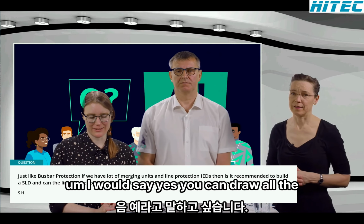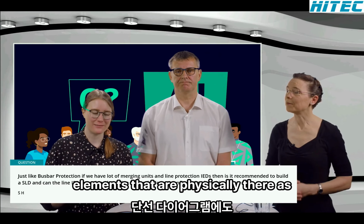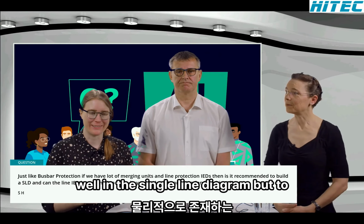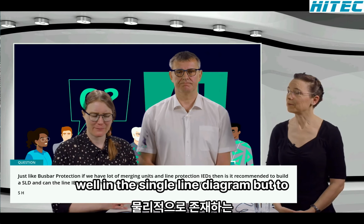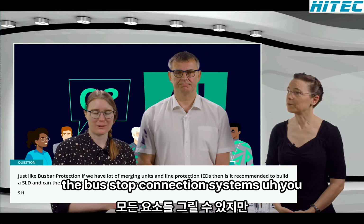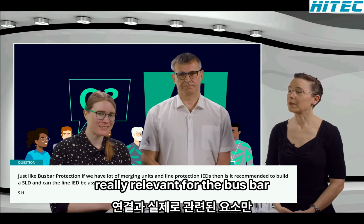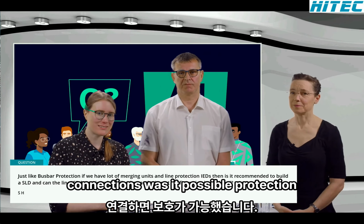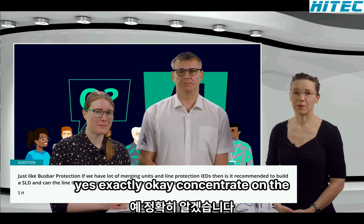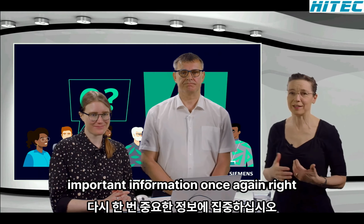I would say yes, you can draw all the elements that are physically there in the single line diagram. But to the busbar connection systems, you only connect those elements that are really relevant for the busbar protection. Yes, exactly. Concentrate on the important information once again, right?